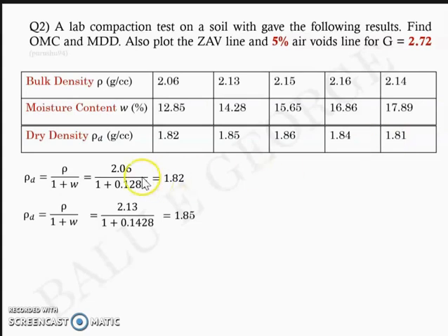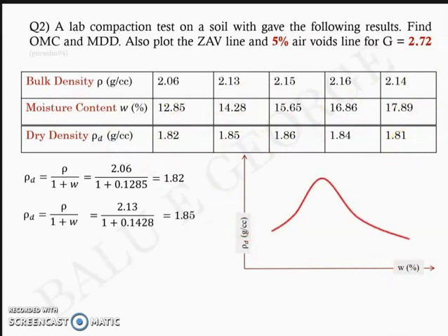So you have dry density here, you have water content here. You can fundamentally draw a plot, which is a compaction curve, based on these set of values: water content, dry density. You'll get a plot quite similar to this, a bell-curved plot, the peak point of which corresponds to a value of maximum dry density and optimum moisture content, like this.